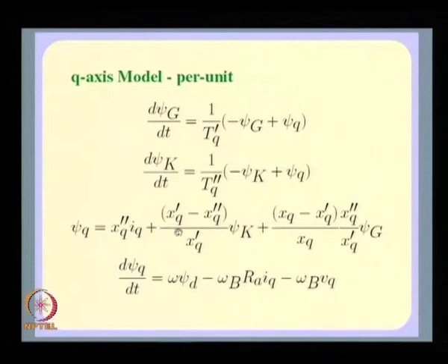Just look at these equations again, you will find that because of doing this, you will get rid of the effect of psi k. Of course, this equation would still be there, but it would be decoupled, meaning the effect of psi k would not be seen by the synchronous generator stator windings at all.